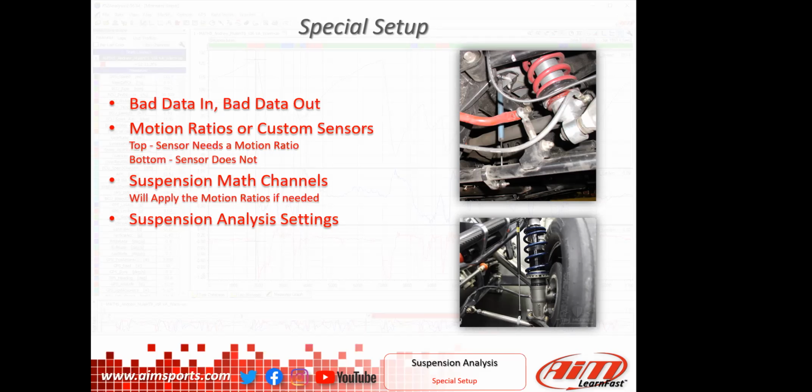So what we also need is another movement of how much the tire goes up and down, right? And then we need to know the track width and we need to know the wheelbase. And then all of a sudden we can do math where we know the pitch and the roll of the car based on the suspension compared to the chassis. And now this is really helping us do a lot of other things, but that's a separate motion ratio.